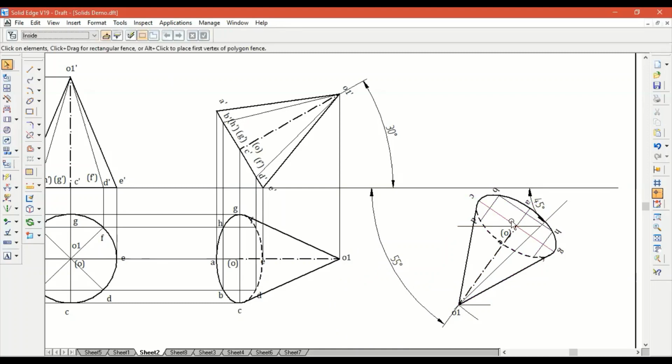It can be clearly seen that all the points in the circumference of the ellipse are visible. So you have A, G, H, F, E, D, C, and P on the circumference. All we need to do now is draw the final front view. Remember, we first have to plot the apparent angle, then move the second stage onto the apparent angle.